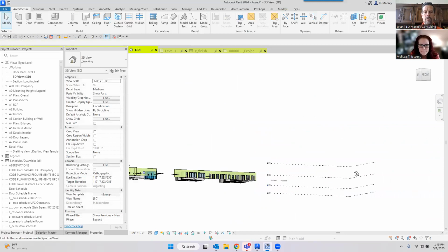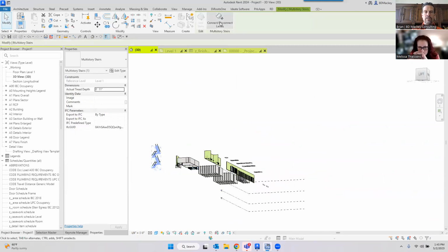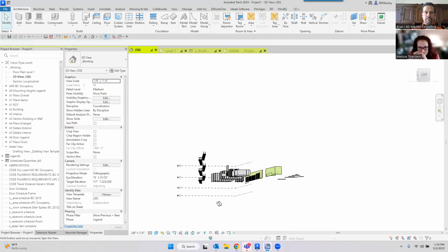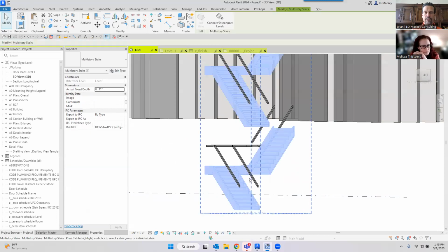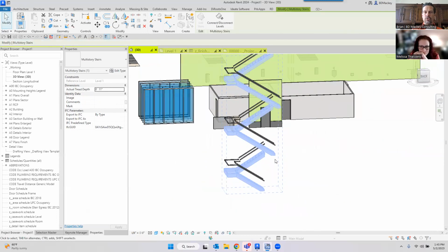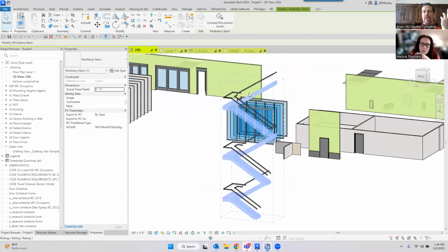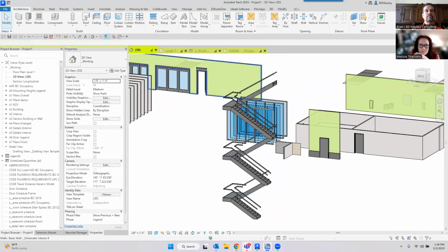So we'll add a level below. We'll come in here, grab these. Say disconnect. We'll connect it to the level basement. Finish. And again, I made that one even shorter, so it just took stairs off of the end of this one. Yeah. So I've got a 10, a 16, and a 12, or something like that. 12, 16, and 14, whatever. Different spacing on those, but it still theoretically works as a multi-story stair.